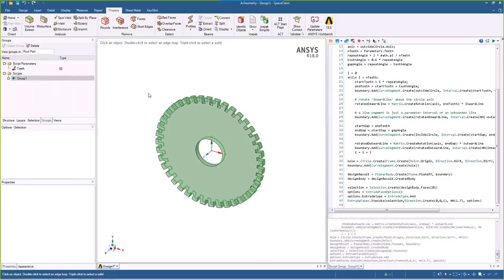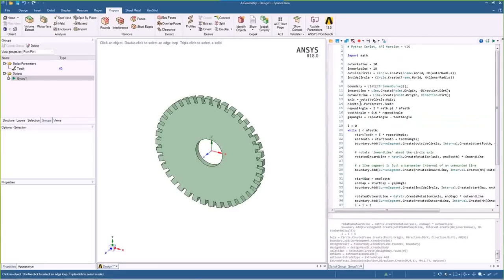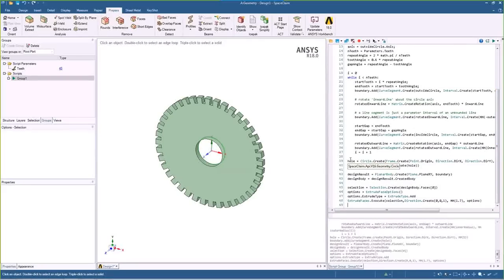So now this is kind of working for us, but we need to delete this gear every time, and we wouldn't want to do that manually. So again, without knowing too much about Python or how all this works, you can record operations. That's a great feature to be able to build your scripts. Just click this record button, and now start going in and performing operations.